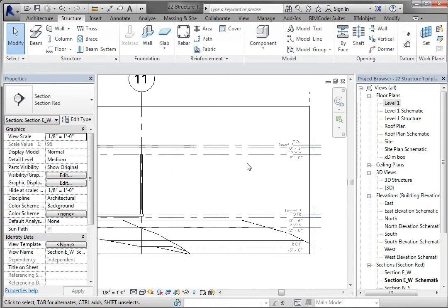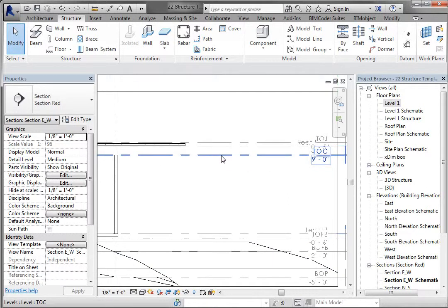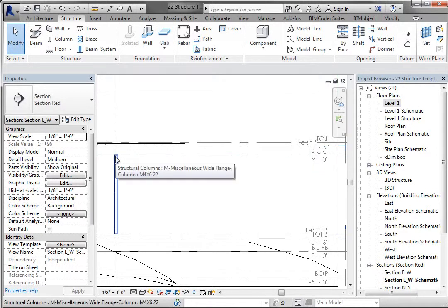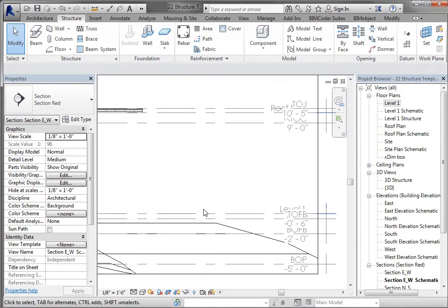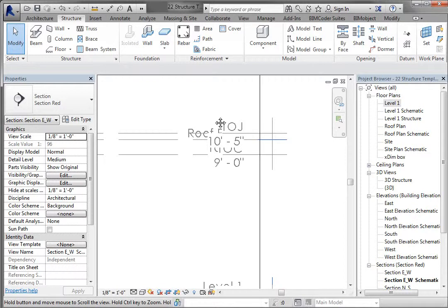You'll also see that there are different levels that I've set up that control the size of the column or where the column's going. Like we picked top of column for that column to be attached to, and so that's working quite well. Now we also have some issues with our levels running over each other, so I'm going to fix that real quick.